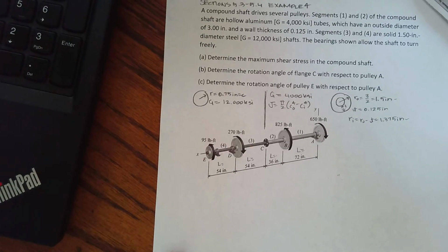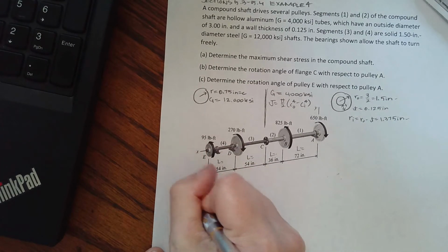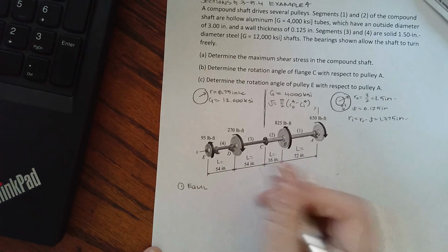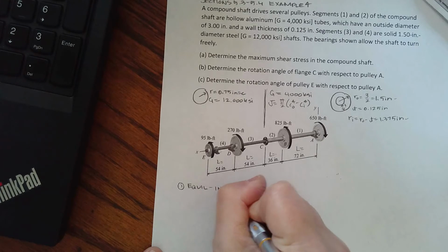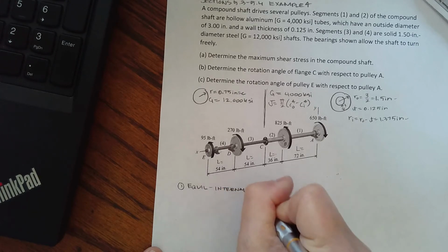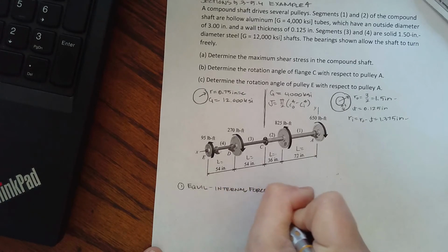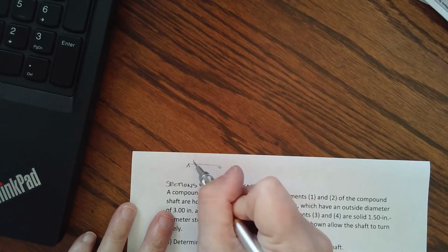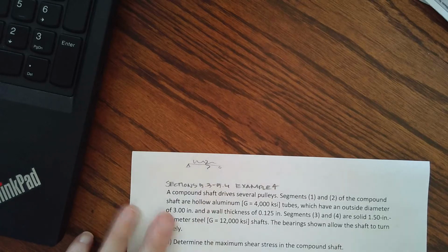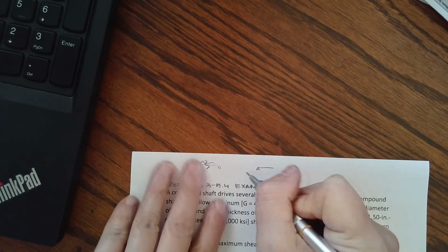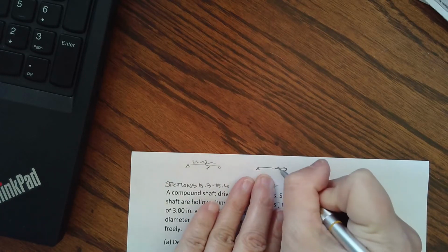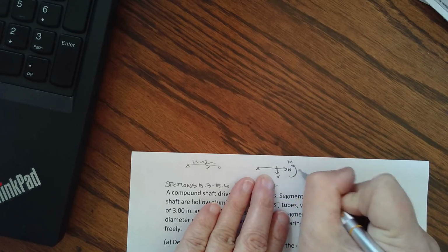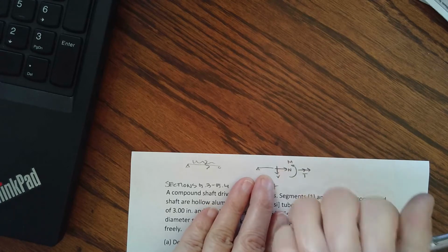So now we have to find internal torque. Number 1, always, we start with equilibrium, which is statics, because we've got to find those internal forces. Just to recap, when we have a beam system like we had in statics and we cut it, then as I'm coming from the left, I have internal normal, shear, and bending moment, and what we ignore is that internal torque coming towards us.